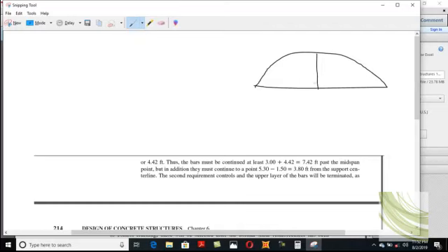So it is necessary that there is a cutoff point. Okay, this is the cutoff point, and this is the cutoff point. The 4 number 9 and 4 number 8 bars, which are right here in between these 2 points, clear?